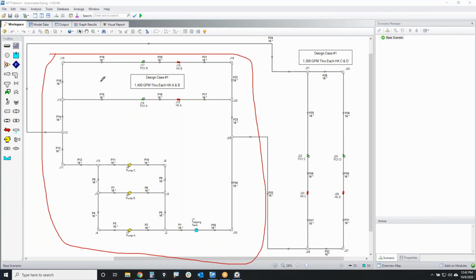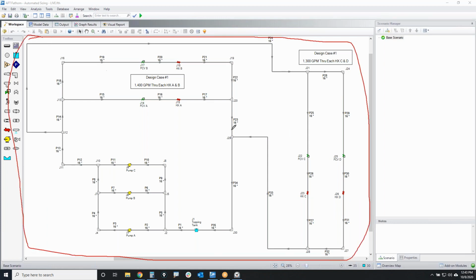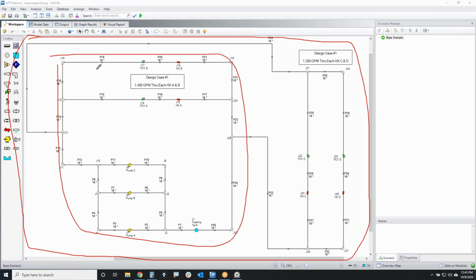was already fully designed, fully sized, and was completely operational. And later on, we were going to be sizing the pipes for this expansion loop. However, in this particular situation, I already know if I'm originally designing this entire system, including the expansion loop, it's a really good idea when you're sizing your main operating system to perhaps account for an expansion loop at the beginning of your design process.